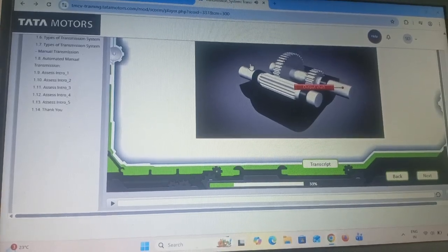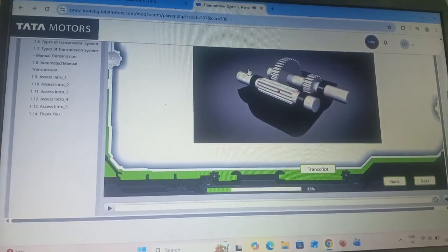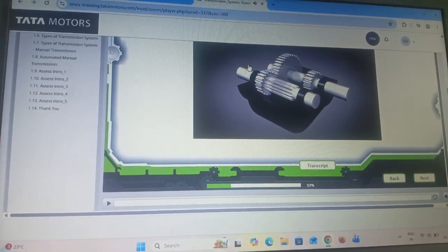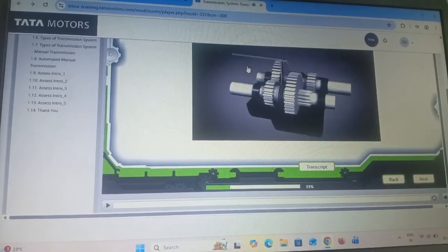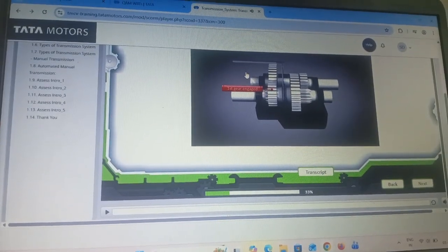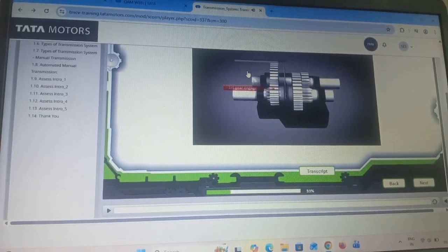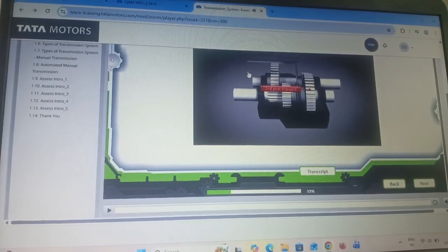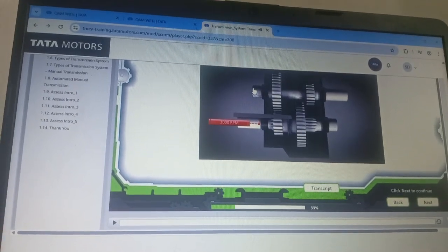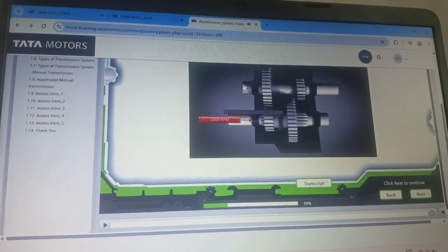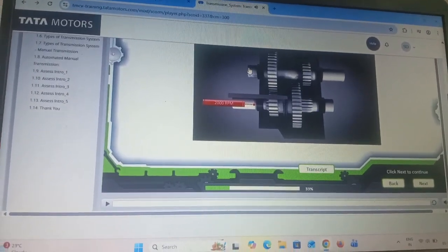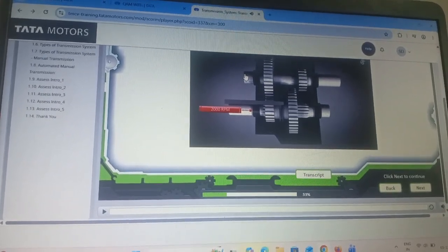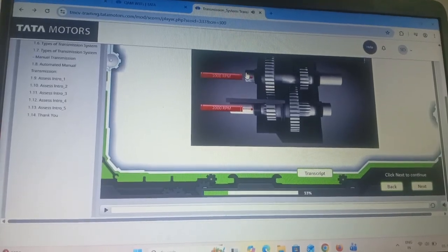2 gear wheels are machined into the output shaft. The other 2 wheels are mounted on a spline shaft. These 2 wheels can slide from left to right and from right to left to change gear ratio. In first gear, the gear ratio is 2 because the driven gear is twice as big as the driver gear. Consequently, the input speed of 2,000 rotations per minute is decreased to an output speed of 1,000 rotations per minute.